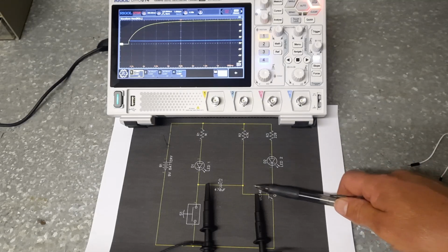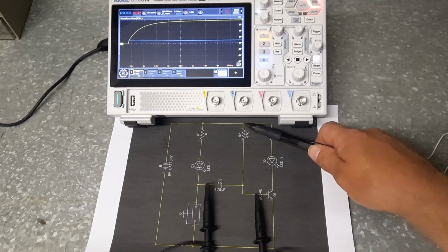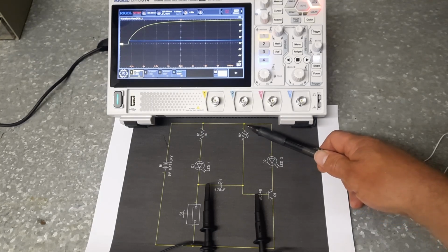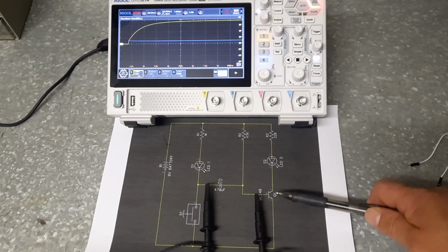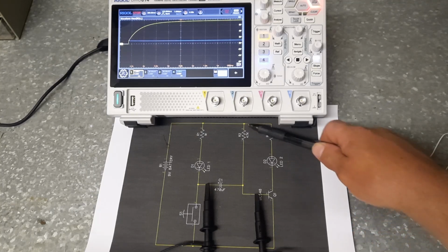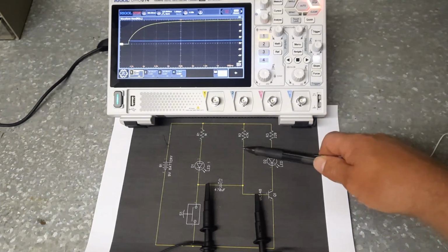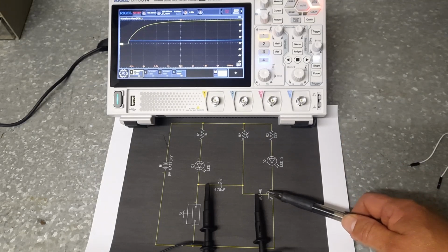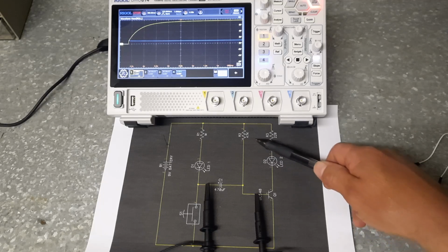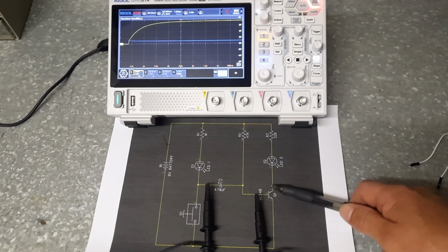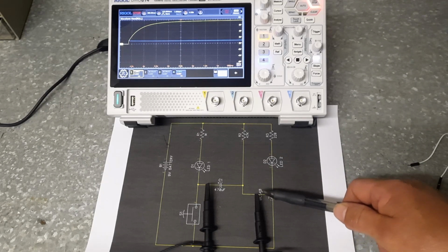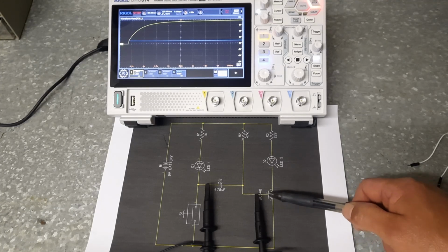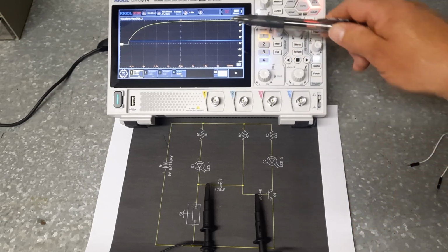It's come down here, and we've had our volt drop across here, which I haven't measured, I haven't worried about it because we know what it is. It's 9 volts minus whatever this volt drop is, and the remainder will be getting dropped across this resistor. But at this point in the circuit, the second we turn it on, this base voltage saturates this transistor. So this turns on, and the base to emitter will drop a constant 0.7 of a volt, which is what we're seeing here.